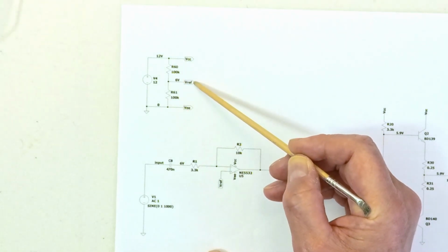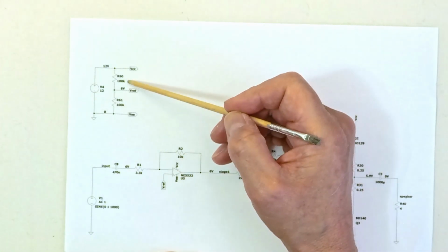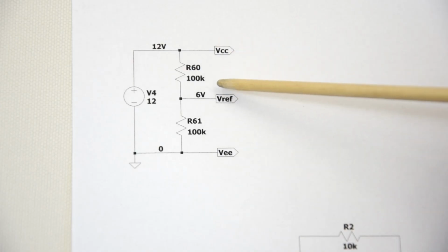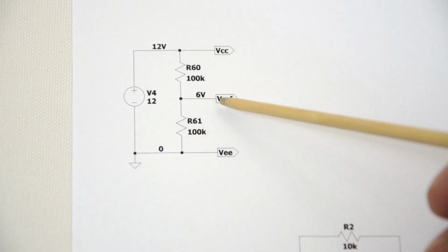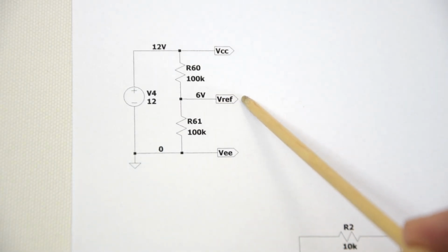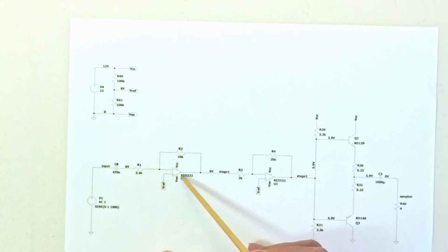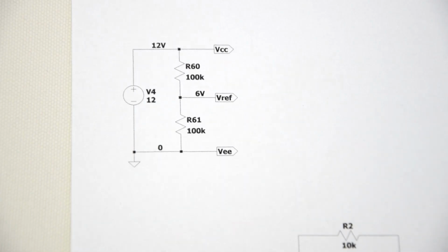It's not stable. The voltage divider has two 100k ohm resistors, so there's only a little current flowing through it. In theory, the op-amps in the amplifier do not draw any current, but in the real world, they can draw up to 800 nanoamps each. An extra current of 800 nanoamps or more can disturb this voltage divider quite easily.